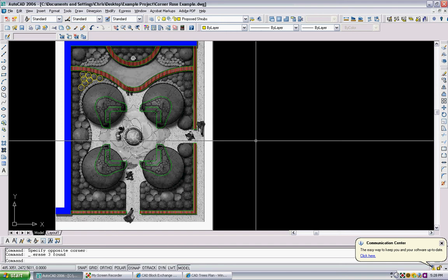The next section is going to be section 3, and it's going to be creating a layout. Understand the difference between layout and model space, and setting your scale through your layout. And I'll show you how to get a 1/2 inch and 1/4 inch scale while still in engineering. So it'll be easy for you to type in 3.5, unless you want to do the architectural way, which is your prerogative. And I'll show you also line type scale and paper space scale and how that applies, and to help your drawing read better. And then we'll do the whole page setup and apply pen settings.